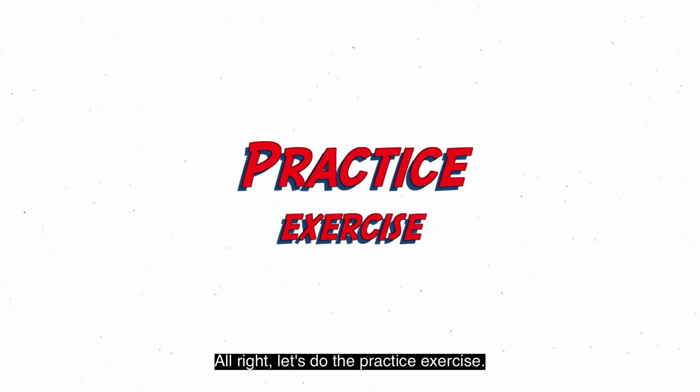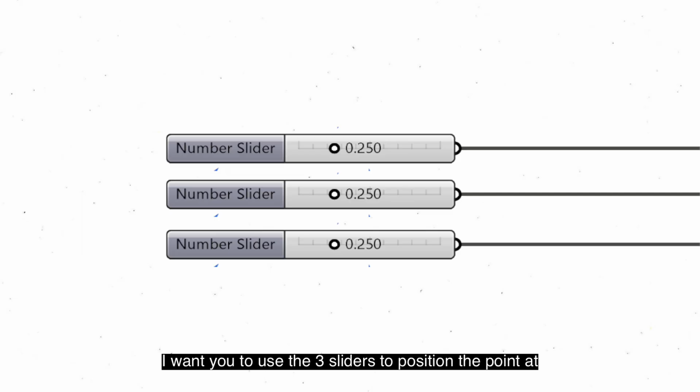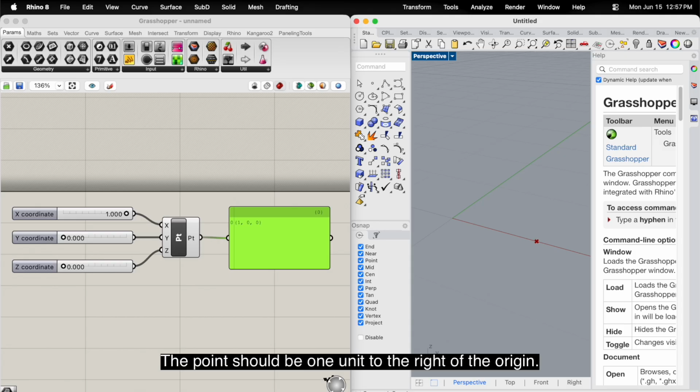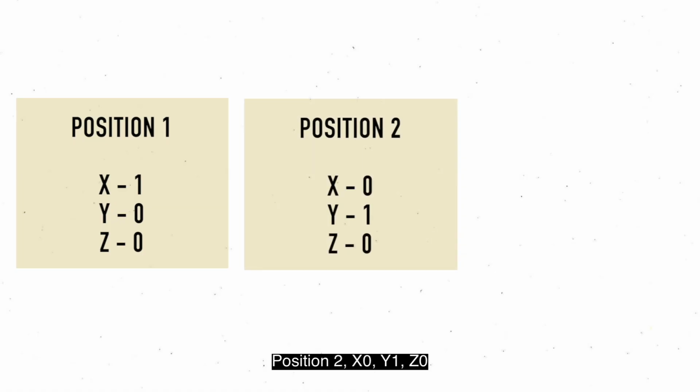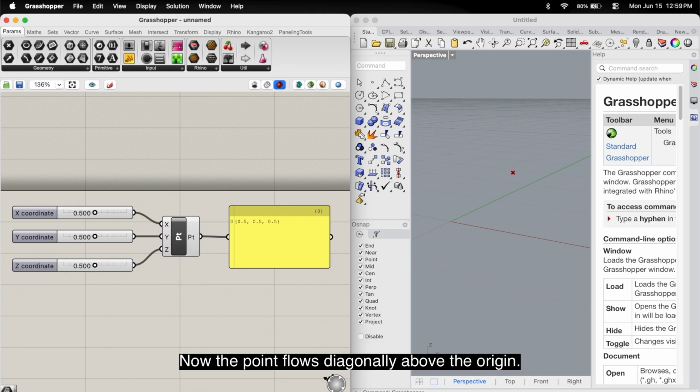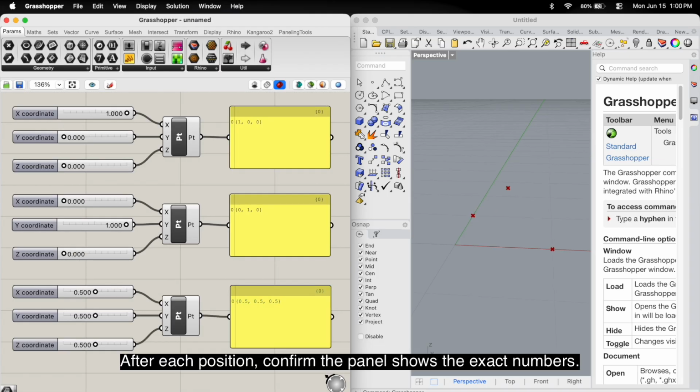Alright, let's do the practice exercise. I want you to use the 3 sliders to position the point at these 3 specific locations and check the panel each time to confirm. Position 1. X1, Y0, Z0. The point should be 1 unit to the right of the origin. Position 2. X0, Y1, Z0. Position 3. X0.5, Y0.5, Z0.5. Now the point floats diagonally above the origin. After each position, confirm the panel shows the exact numbers. If it doesn't match, your wires might be crossed. Double check which slider connects to which input.